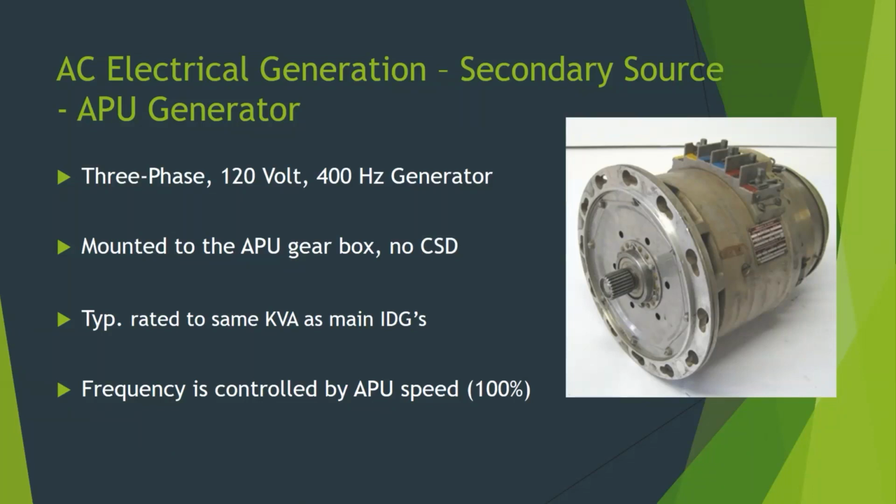With APUs, auxiliary power units, we'll talk about those in a later lesson. They're a small turbine engine, in addition to the main engines on an aircraft, that typically can be started using a battery DC starter. Their primary purposes are to drive electrical generators and also to be a bleed air source for powering bleed air operated components on the aircraft.